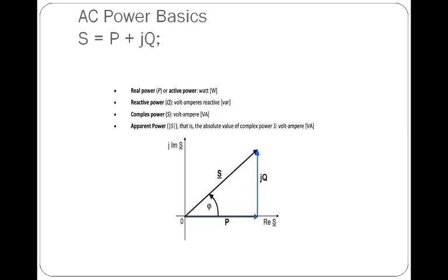We can simply multiply current by voltage to get the true power in watts. If the load is, however, purely reactive, then the voltage and the current are 90 degrees out of phase. That's phase angle is 90 degrees. For half of each cycle, the product of the voltage and current is positive, but on the other half of the cycle, when we have a sine wave, you have a part that is positive and a part that is negative.